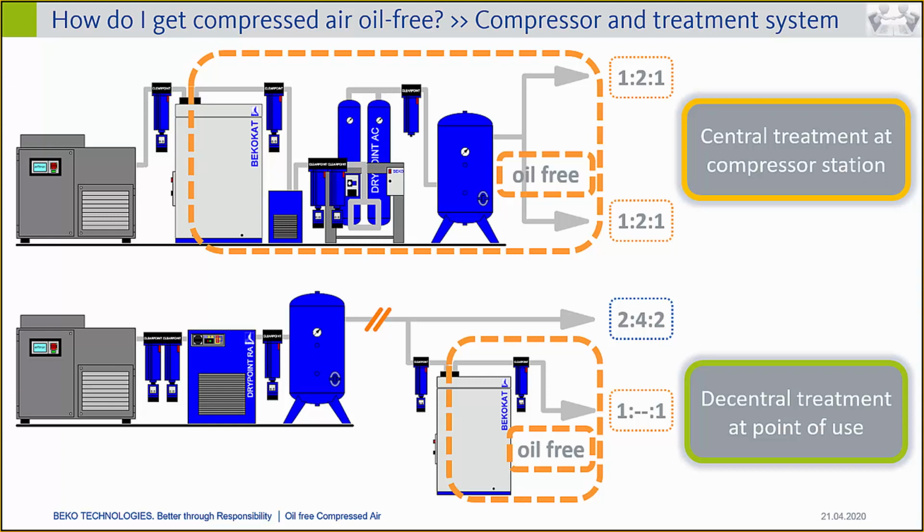Yes, sure. There's one point, there's no need of using a pre-filter upstream of the BEKO, there's only a water separator on the picture, is that correct? Yes, in that installation it is correct, because the water separator is good enough to avoid any droplets entering the system, and in that case it's okay for the BEKO. I wouldn't say that is a general recommendation.